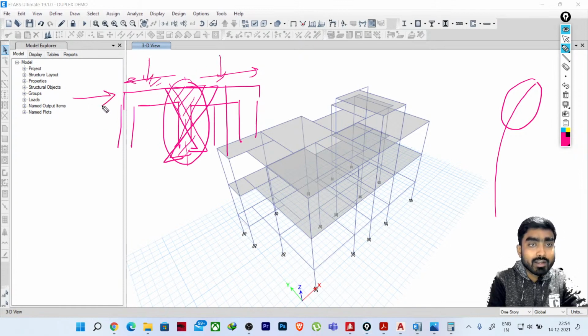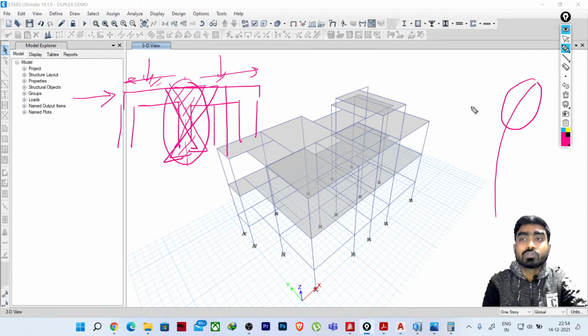Then when you have a lateral force, that will be different. So at the top stories, the unbalanced moment used to be very high, when you have earthquake loads. So that's why you will be having higher reinforcement at the top story. If it is a small structure, you can always continue the reinforcement at the top from the bottom. We should do that only.